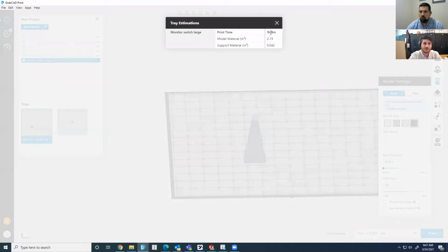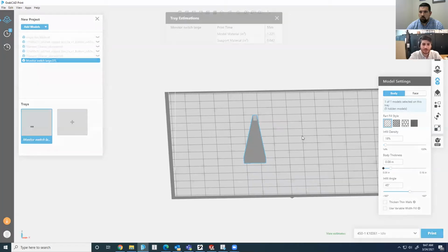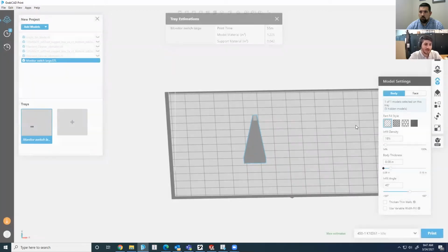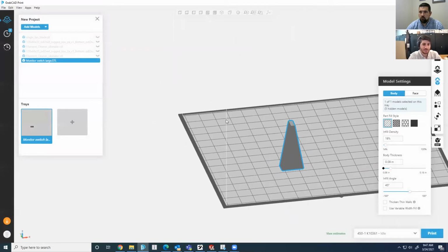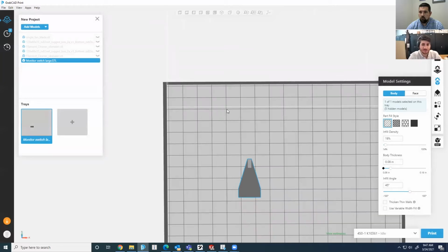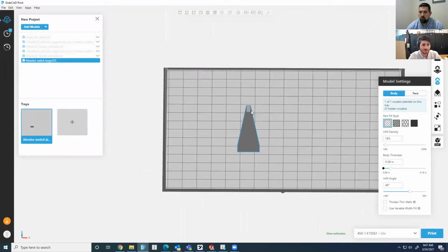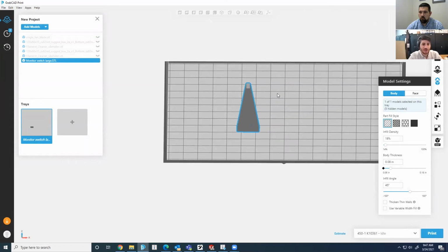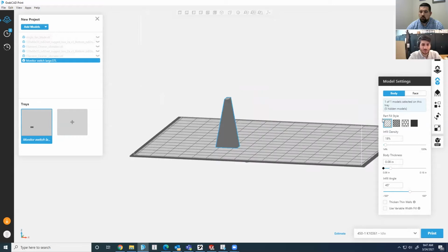So with a solid infill, it's an hour and 8-minute part. And when I change this to sparse infill with an 18% infill density and a 0.8 body thickness, it changes to 55 minutes. Not significant, but when you look at the size of this part and the actual build time, 10 minutes is a fairly decent savings when you're trying to get into a design meeting, or if you're working through different revs of a prototype and you want to make sure that the fit works well for your assembly or project. That's a good thing to definitely save time.